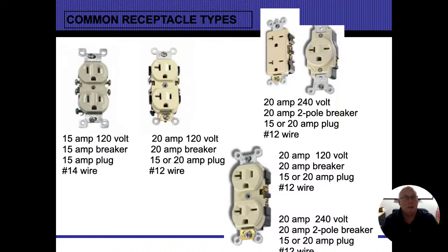So many times, in conduit areas like where we live here in Chicago, we're not going to run separate ground wires to these outlets. We use the conduit that comes in there. So we really don't make a connection to that ground wire or that green screw, because those little plates at the top and the bottom are screwed into the 1900 box, or the outlet box. And as long as I have a metal connection, then that outlet will be grounded, plain and simple.